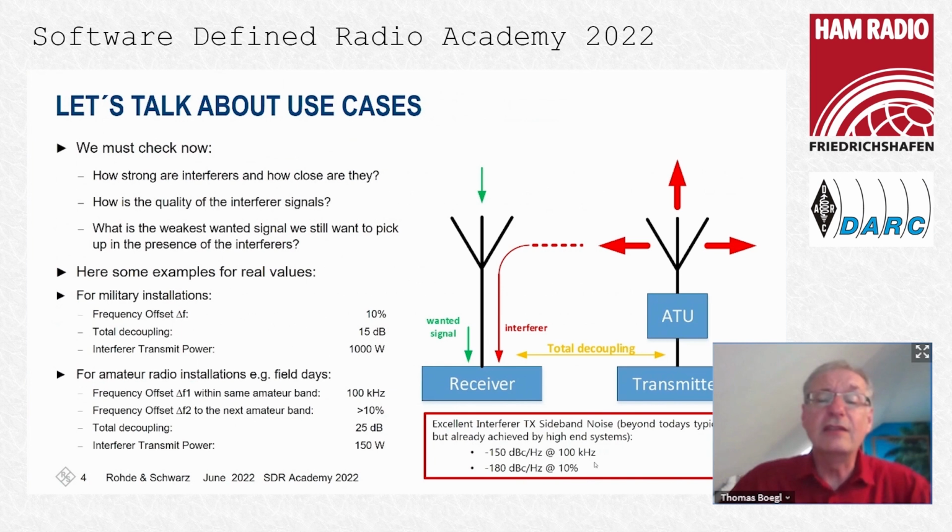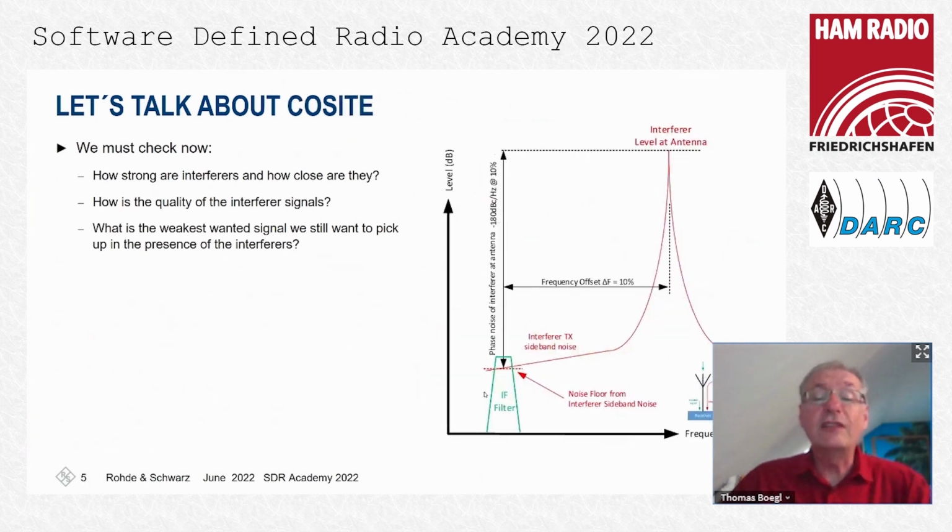And by the way, the filters used for getting the spectrum clean are also used as a pre-select in the receiver case, because if you can imagine, if we are changing the direction in a transceiver configuration, then it will be good to have this high quality filter inside the transmitter chain also used as a receiver front end. Okay, let's look at the spectrum situation and ask the same question and see how it looks.